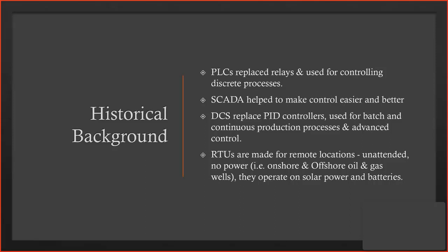Then DCS evolved and replaced the hard PID controllers, and DCS were primarily used for batch and continuous production processes, and after some time it advanced into advanced control. So discrete PLC, SCADA, DCS, and then there is also RTU. RTU is a remote terminal unit, which is the same thing as a PLC. There is no major difference between PLC and RTU, but RTUs are specifically made for remote